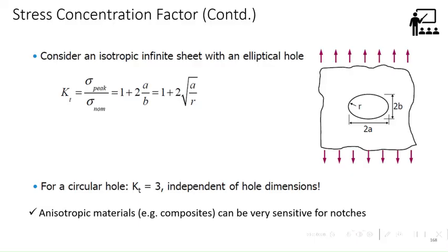Obviously, your metal is homogeneous. But in composite, you make a cut and create a discontinuity as a whole. The cut acts as a potential local stress raiser. Even to minimize that, you cover it with adhesive, or close it. Imagine a composite plate, you make a water jet cut. Nobody uses a drill bit. You have to do a water jet cut. Still, if you use a drill bit, it is the worst case.